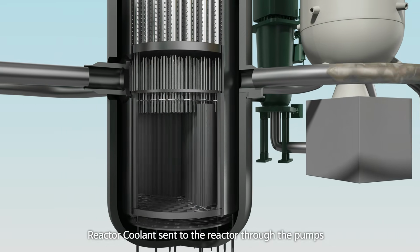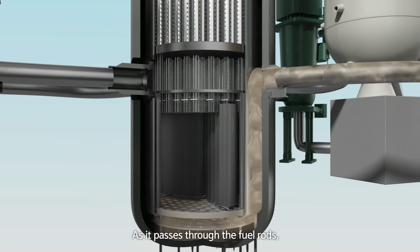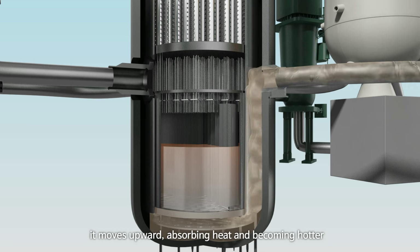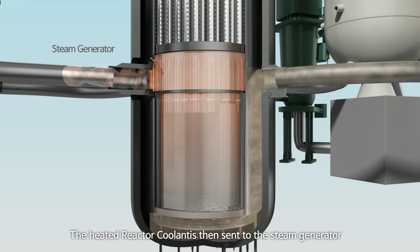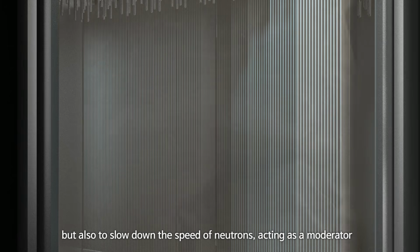Reactor coolant sent to the reactor through the pumps hits the walls and then moves downward. As it passes through the fuel rods, it moves upward, absorbing heat and becoming hotter. The heated reactor coolant is then sent to the steam generator. Reactor coolant flowing through the reactor serves not only to transfer heat, but also to slow down the speed of neutrons, acting as a moderator.